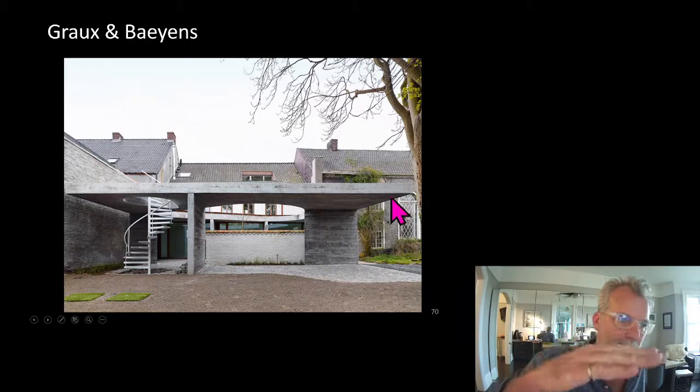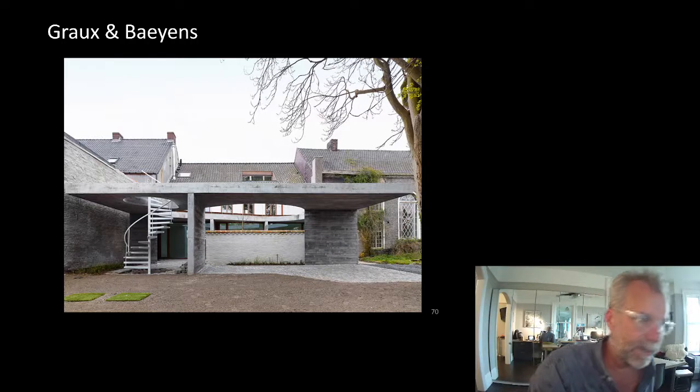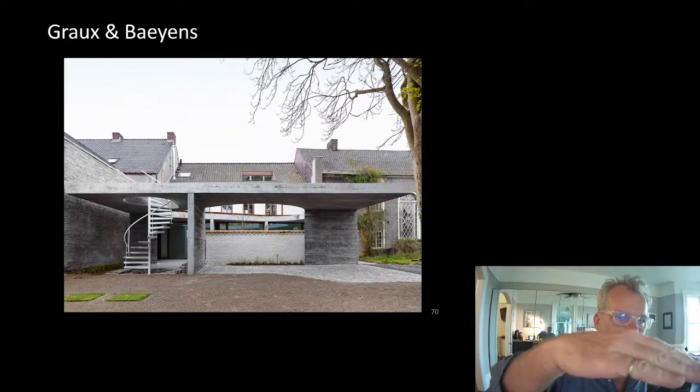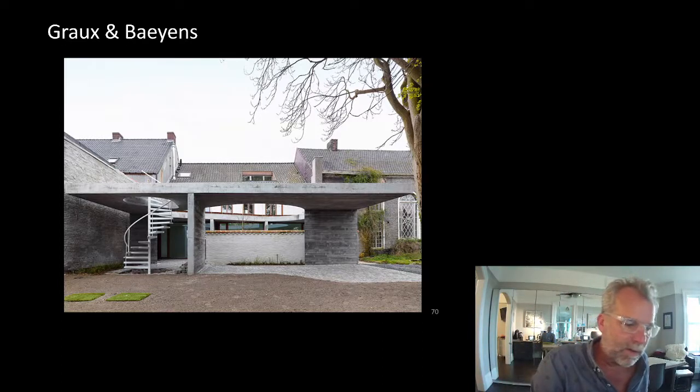We tend to think of our immediate elastic deflection, and that's easy to understand. But concrete creeps. So if, when the concrete is cured and the shores come out, it then sags 20 millimeters, you can count on it being 60 millimeters of sag by a year or 2 years from now. The long-term to short-term ratio is about 3. So canopies in cast-in-place concrete are amazing, but you have to be very careful about sag.